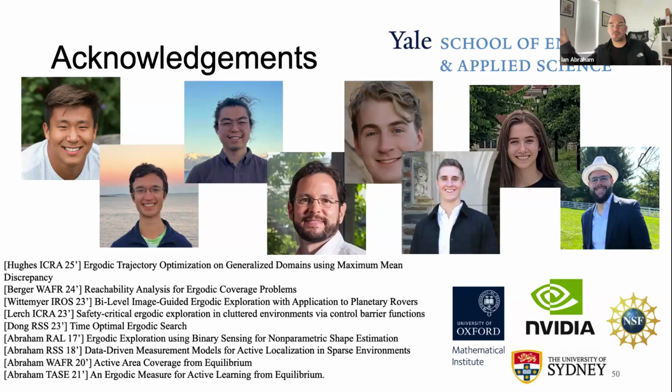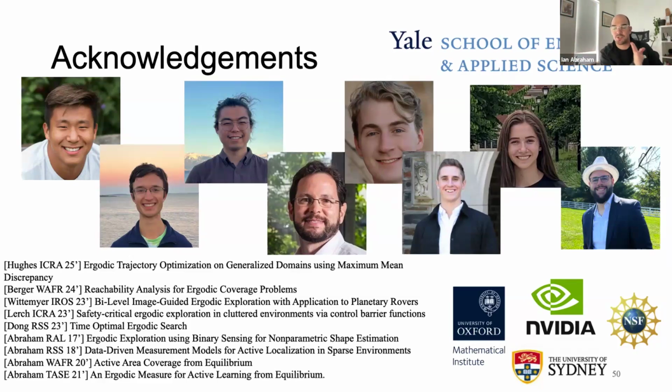If you have more points, the approach would try to spread out more coverage. I think TSP is saying, if I have exactly n points, I will give you n trajectory points. In ergodic control, we can be flexible. We can say, I have way more points, spread out the sampling, right? And that's a nice robustness argument, right? I like to sample more points in more regions, so include more redundancies, because sampling once is not useful. You don't just sample once in one place, you sample many times, because noise is going to be a problem. So in the perfectly exact scenarios where you have exactly the same number of points and you discretize your space, I think they would be exact.